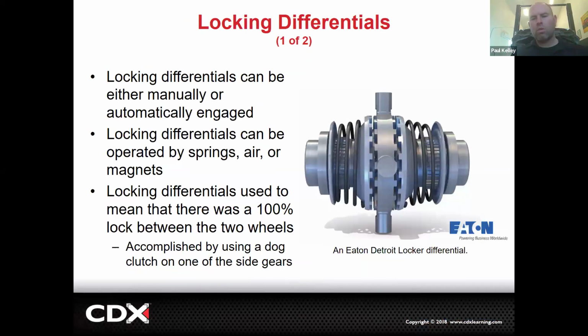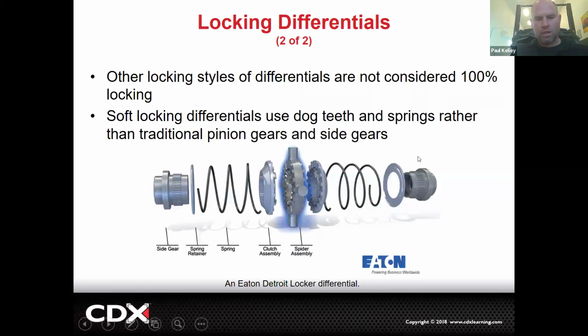And then there's a whole bunch of different types of full-on lockers, right? No clutch. These ones actually just engage. They're using dog clutches. So if you get spinning fast enough, I've got to get the mouse over here in the right spot. This axle will be splined to this plate, and it'll actually engage right here and lock on that like a manual, almost like the dog teeth. Click, it'll be a full-on lock. But other types, they do have more like a soft locker that'll not really exactly lock, but kind of grab, but they make a lot of different stuff.